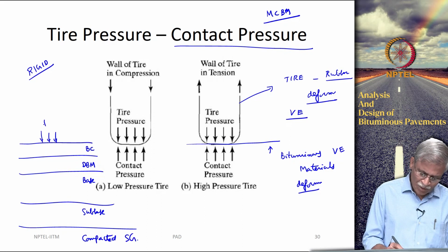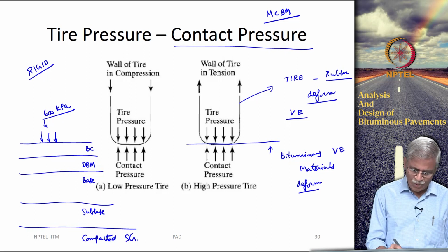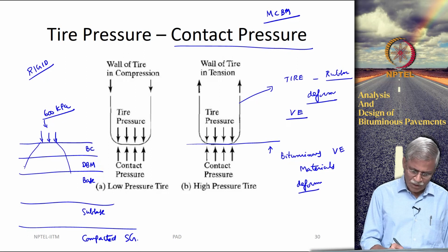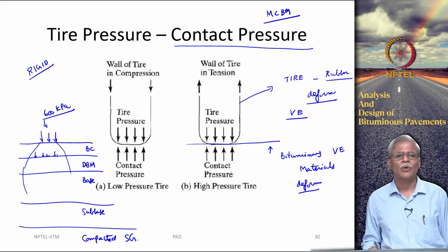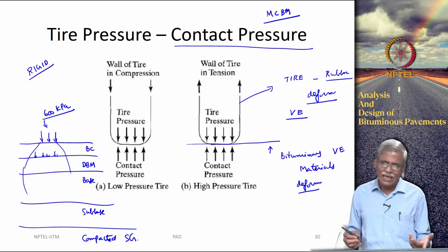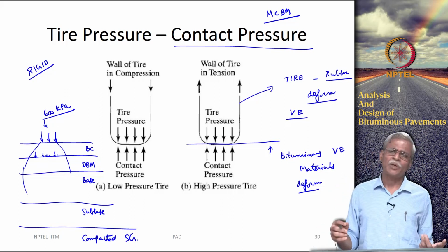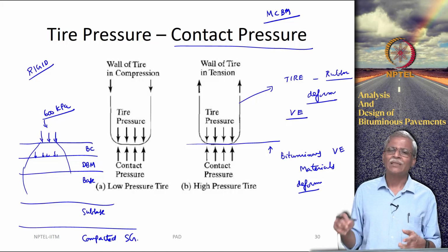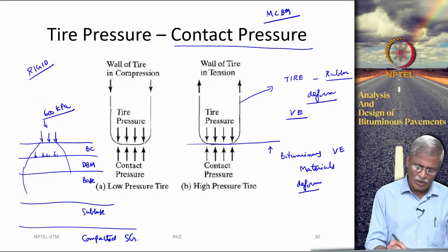So, you are only going to be interested in how much load is transferred, because you want to use this and do your calculation. So, how much are the stresses and strains that are transferred at different locations. And if I say that you do not need to really worry about it, whatever is the pressure in the tire is the contact pressure.